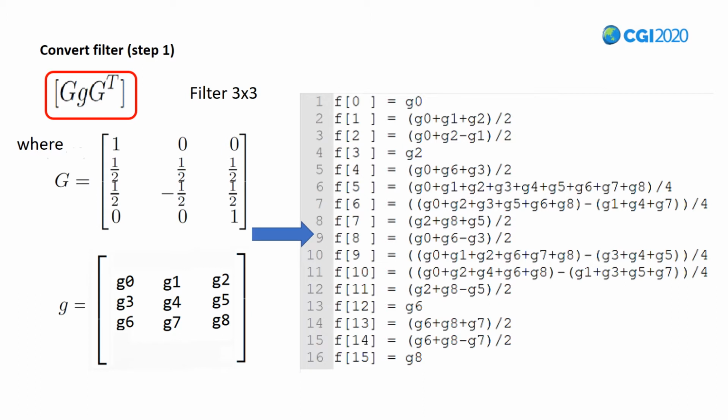Compared with the input data, the filter data is relatively small in size, though with the same number of channels. Despite that, this step contributes only a small percentage to the total performance. The storing method and the access pattern could have a huge influence on step 3, the dot product step, because each input tile needs to perform a dot product with all filter tiles. Since matrix G is small in size and very simple, the 2-pair matrix multiplications can be expanded to additions and only 12 multiplications.